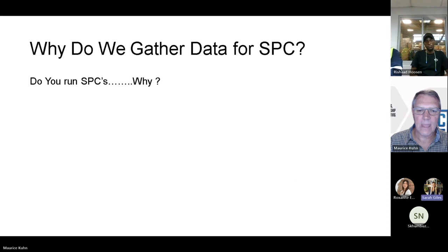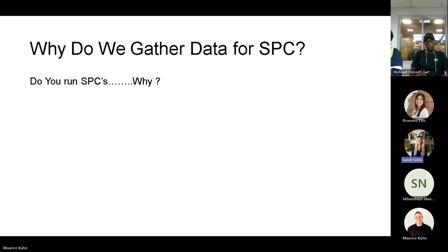We see in our business various processes, not your typical SPC with control charts and things like that. And then we use it more for trend analysis, basically looking at, and that's what SPC is. You want to pick up that a certain control within your process is going to go out of spec before it goes out of spec.